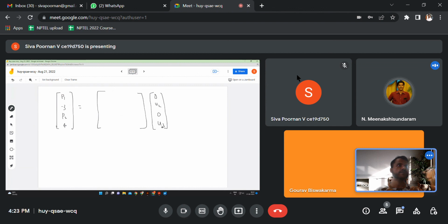Is this fine? This is how we solve: as we said earlier, whenever you have a displacement to be 0, there you have an unknown support reaction. And wherever you don't know the displacement, that's where you apply the forces. The forces would be either 0 or known. That is why it always happens that you either know the forces or the displacements. Both being unknown can happen, but we don't want to study that first, at least starting out.